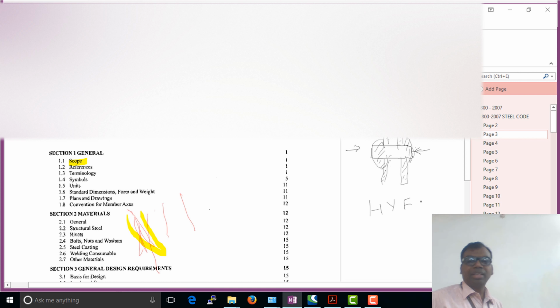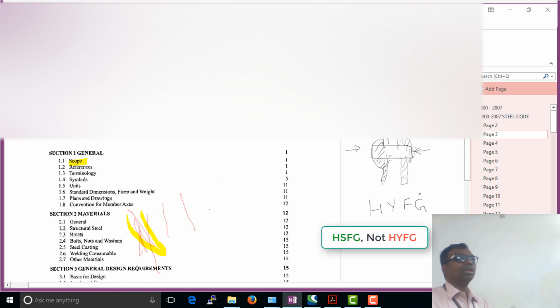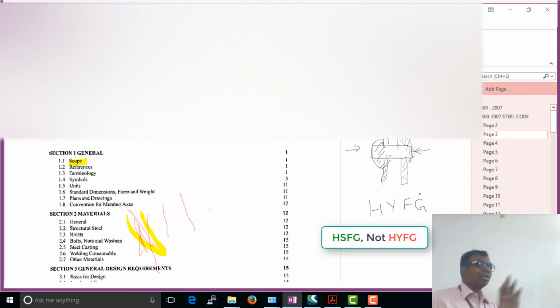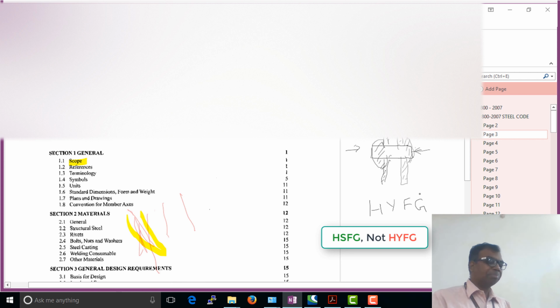Okay, so these bolts are able to achieve the same property of rivets, and all the other desirable properties, like you can remove it and then attach it again, all of that is possible. If you look at bolts, there are two kinds of bolts. Usually you call them black bolts. Black bolts are just bolts which you use for temporary holding. Before you actually do a connection, you may just have to hold the pieces in place, so at that time you use the black bolts.